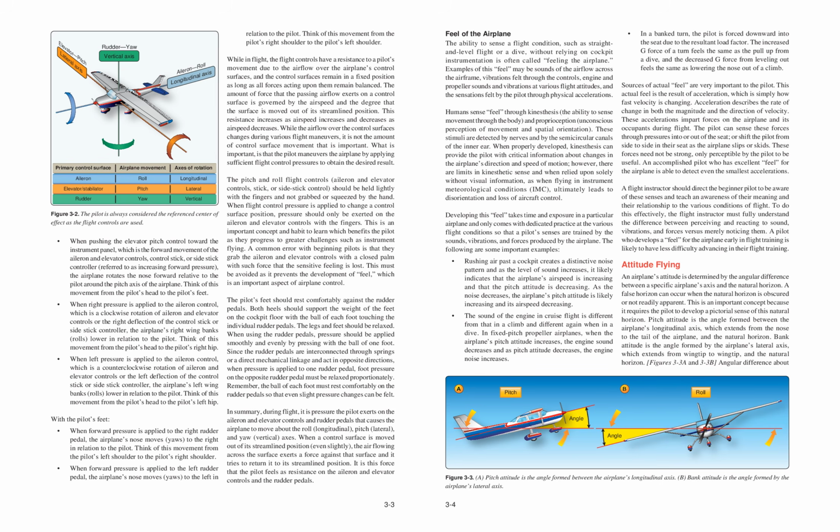While the airflow over the control surfaces changes during various flight maneuvers, it is not the amount of control surface movement that is important. What is important is that the pilot maneuvers the airplane by applying sufficient flight control pressures to obtain the desired result. The pitch and roll flight controls, aileron and elevator controls, stick, or side stick control, should be held lightly with the fingers and not grabbed or squeezed by the hand.